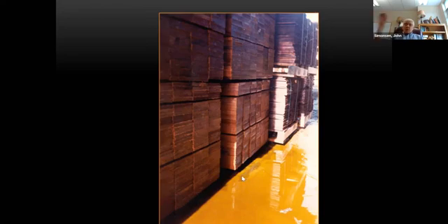In the old days, greedy treaters, in the springtime when they had lots of orders, because winter's finally gone and everybody wants to start building decks or whatever, they would truck dry the CCA. So they would treat this as CCA with this yellow color. It's water with copper, chrome, and arsenic in it. So they would call it truck dry and kind of chuckle. But what would happen is they'd load the wood wet on the truck and then ship it to Home Depot. And it would be dripping arsenic and chrome and copper on the highway as it drove down the highway.